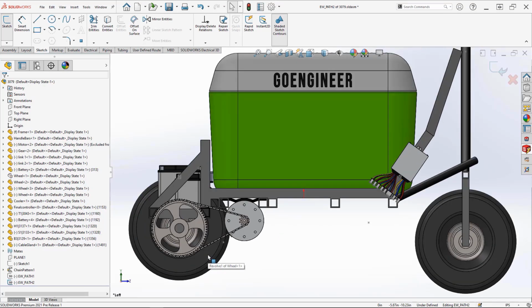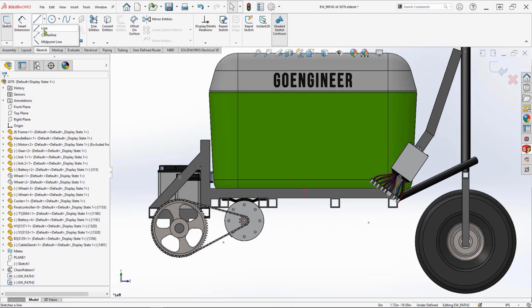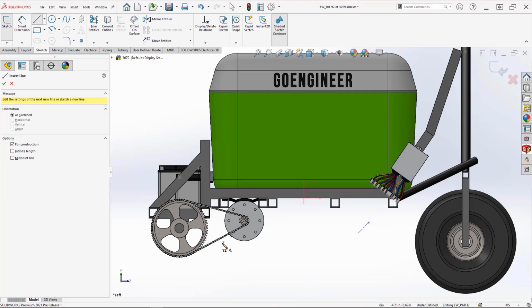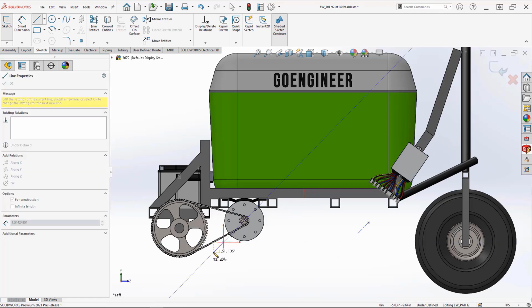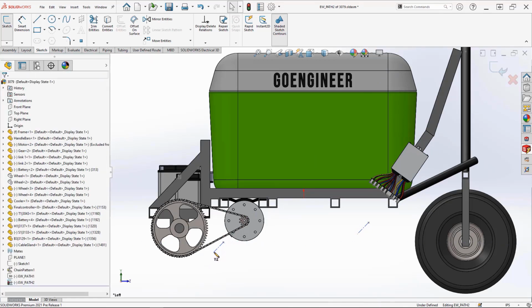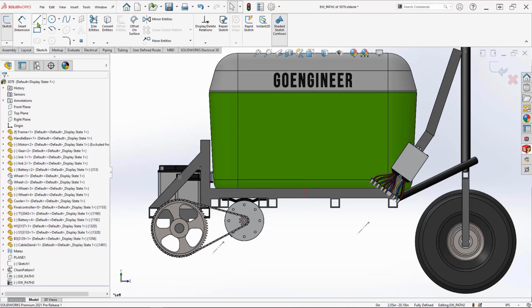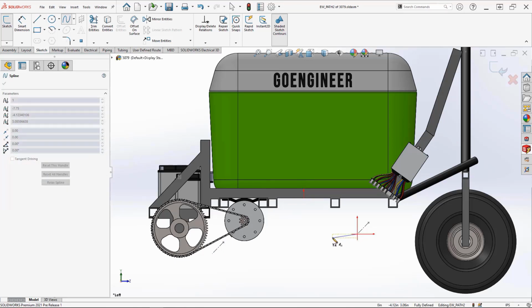What I'm going to do here is I like to hide things that I don't need, and I like to do center or construction lines in order to define little straight line segments. I do this because the routing engine doesn't see the construction lines, but I use them to define my point in space and lock my routing path in reference to something, because sometimes it gets a little confusing when you're doing 3D routing. So I set those up.